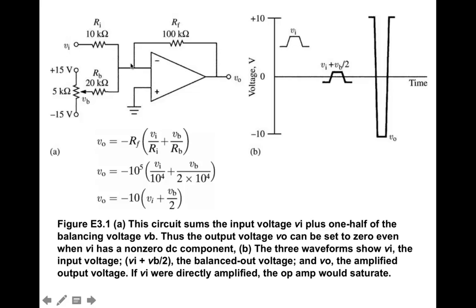So what actually comes in to your amplifier is just this shifted signal. Now, because the input voltage is applied here to the 10K, but you also are adding this particular voltage, your new input voltage is considered to be the sum of these two voltages. And so, for your equation, because op amps are linear, you can consider each one of these inputs to be like an inverting amplifier.